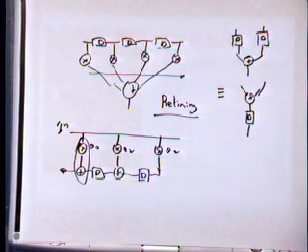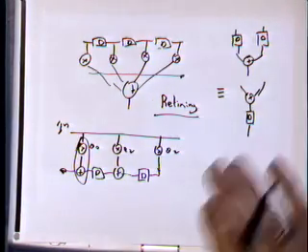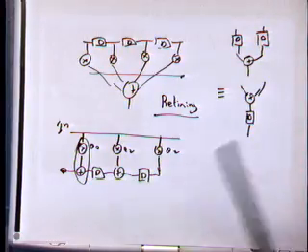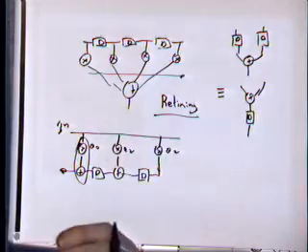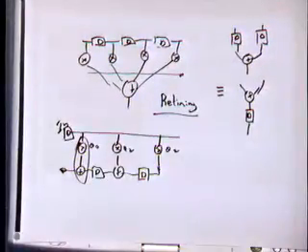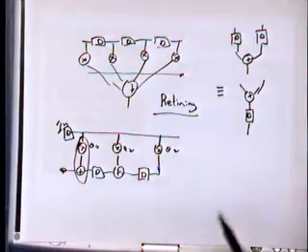Now there's one more thing you could do, which was not 100% clear if it's within the rules. Nobody did it. I could have gone one step further. I could say, assume that I can delay the output by 1 clock cycle. I'm not changing anything in the performance, but I'm just going to put some extra delay in. As I said, it's kind of on the edge of what was allowable, because you changed the response, because everything is now appearing 1 clock cycle later. But if I just inject the delay here at the input, I can do that. It's basically just saying my output is going to appear 1 clock cycle later.